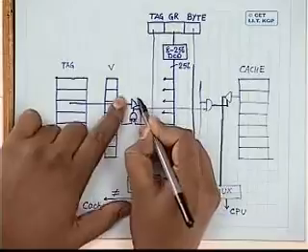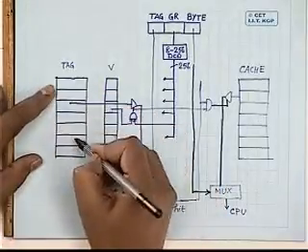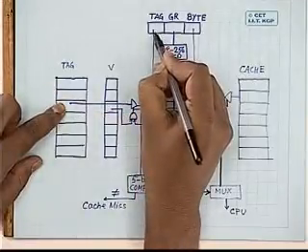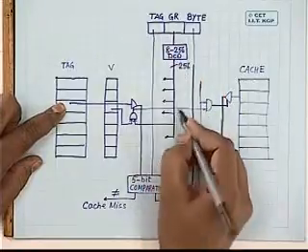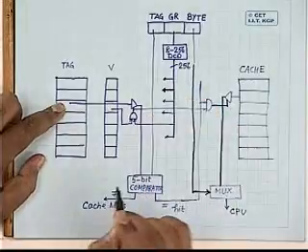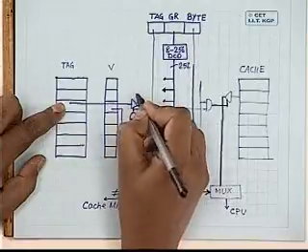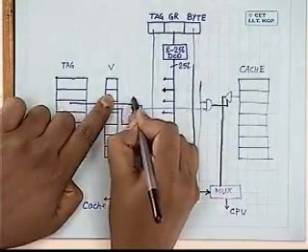It may so happen that I get the data from some other location in the cache memory and which matches with this particular tag field. So suppose this output of this comparator is active. In case this output of the comparator is active, I will have a similar AND gate here, which will be ANDed with this valid bit.